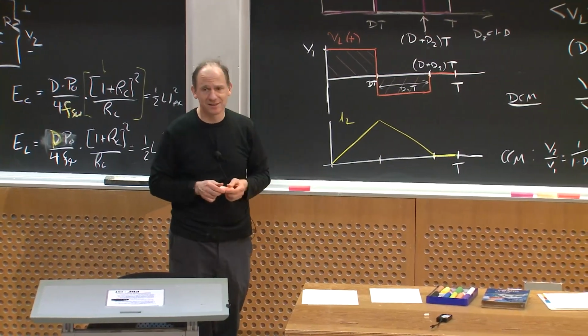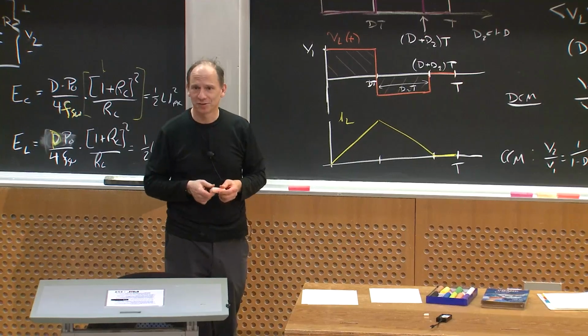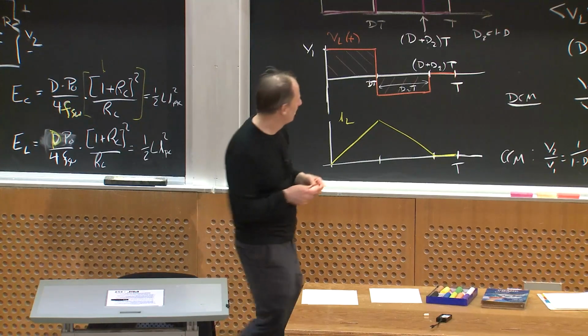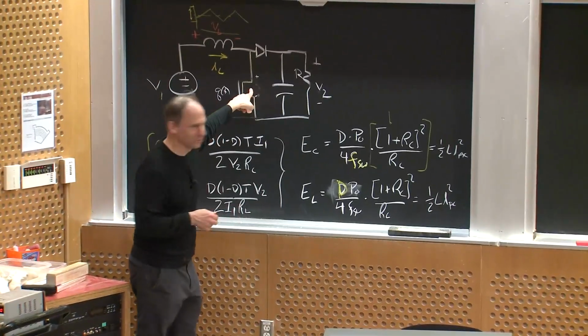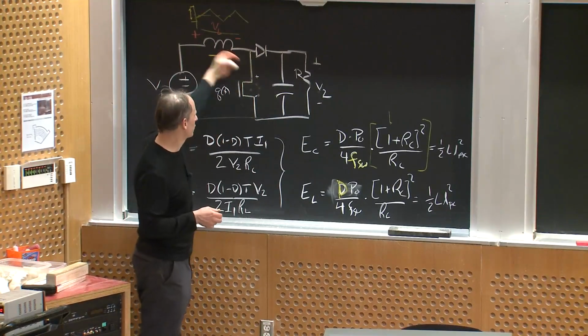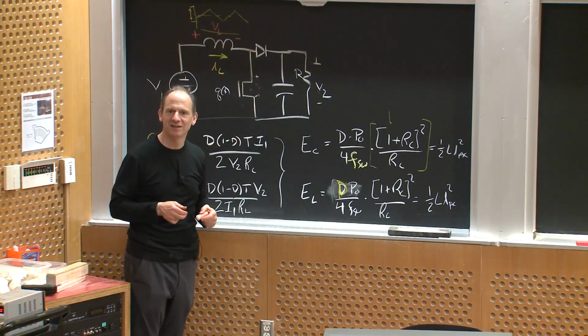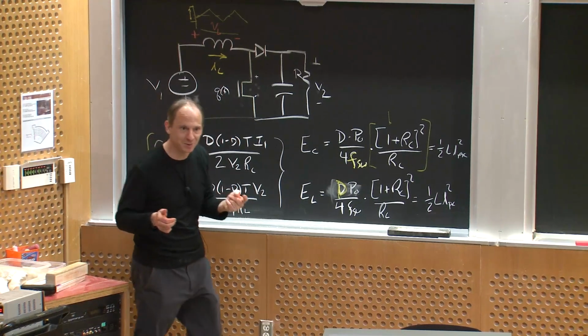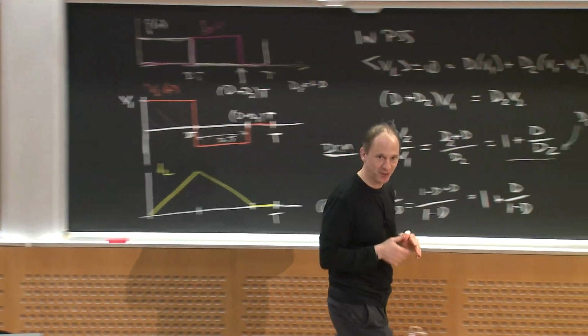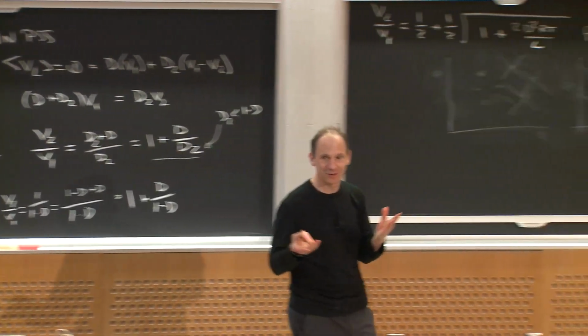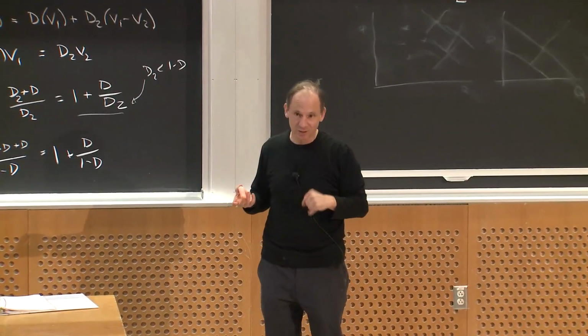I actually did that this morning on our demo converter too, but that's not what happened. What happened was the MOSFET started breaking down. It would just start dumping energy into the MOSFET, which isn't good for the MOSFET. Fortunately, I didn't kill the demo by being stupid and taking off the load. But the point is you don't necessarily have to get to periodic steady state in all converters, and this is an example where you can get to really high voltages.